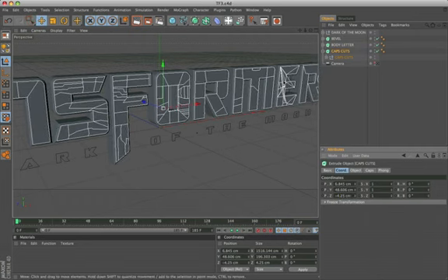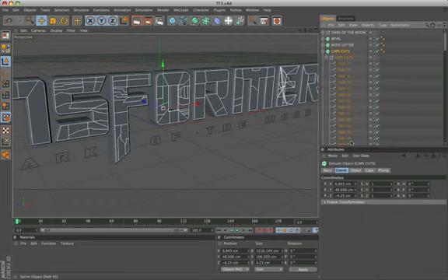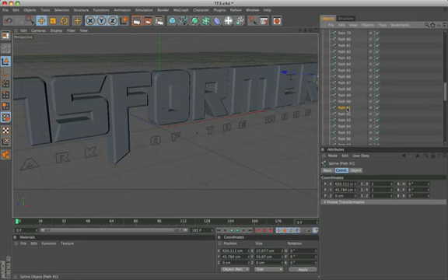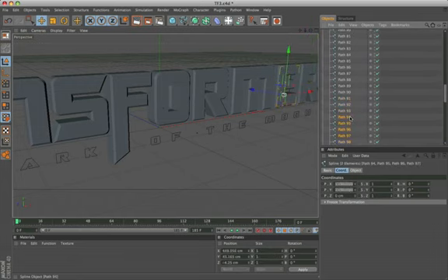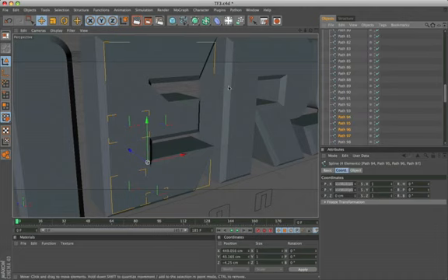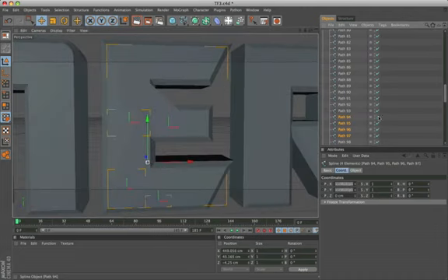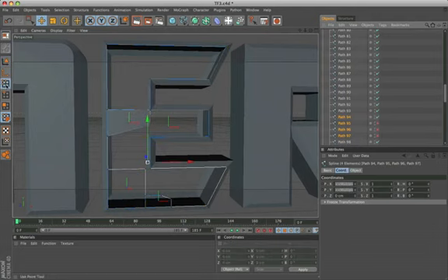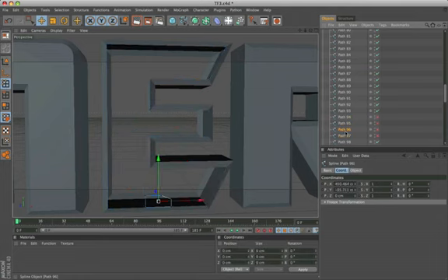As we can see, the E letter has an extrusion problem in some paths. We select the paths from 94 to 97, and activate the Points tool. The problem is in path 95, because there is an overlap point.